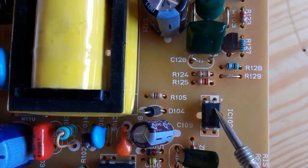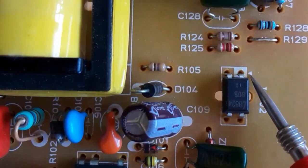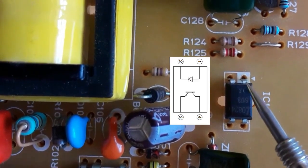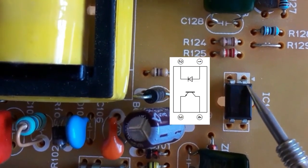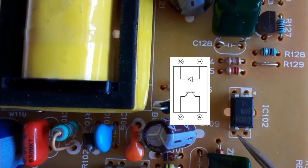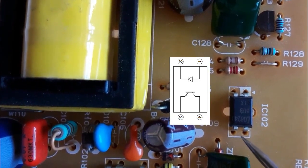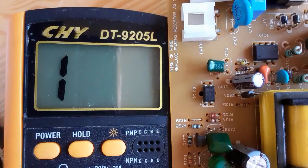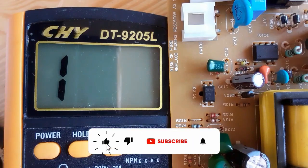Always first locate the first pin, okay? Pin number 1. Pin number 1 is connected to the anode and pin number 2 to the cathode. And of course, pin number 3 and pin number 4 are connected to the collector and emitter of the phototransistor. So let's check this optocoupler now using the multimeter.